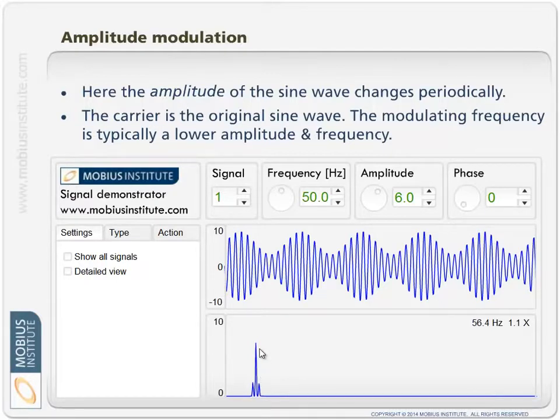In fact, you might see situations with electric motors where you have a peak at the rotor bar frequency, and on either side of that is a peak at twice line frequency. So it will be separated by 100 Hertz or 120 Hertz. But you may have a situation where the peak at the rotor bar pass frequency is not all that high in amplitude. The peak at that frequency minus twice line frequency is maybe quite small, but the amplitude of the peak at rotor bar passing frequency plus twice line frequency is actually quite high in amplitude, and in fact it might dominate that part of the spectrum.